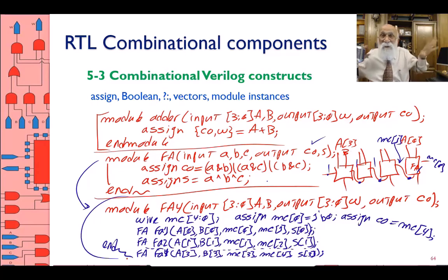All right. We are covering a lot of things. Make sure you understand all of this, then you understand everything we have said so far. So I have added in two ways. This is obviously easier, but then if you want to do individual adders, and then you want to go inside the full adders and do the gates, and then inside the gates go do the transistors, this can become much more accurate timing wise than the just single assign.